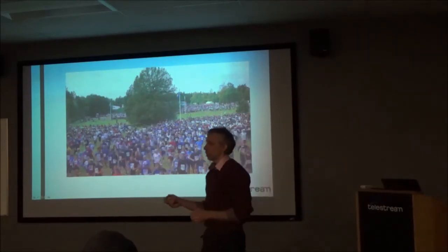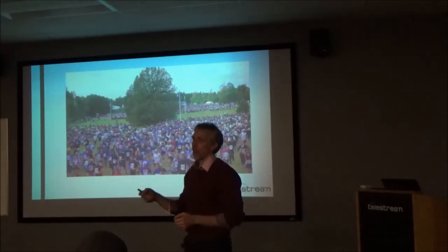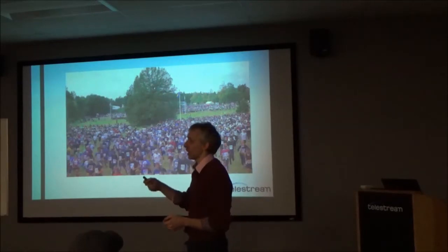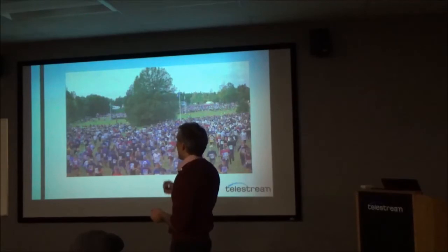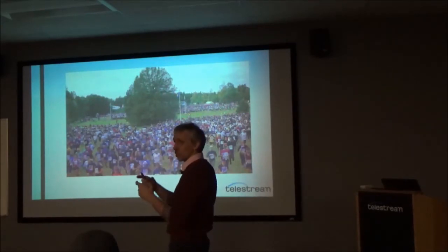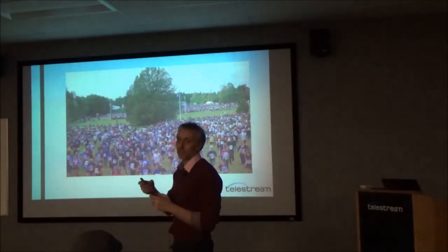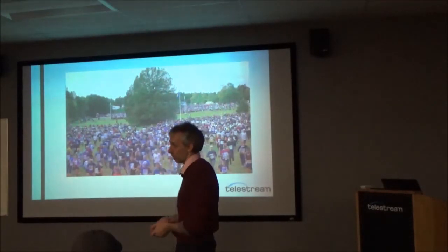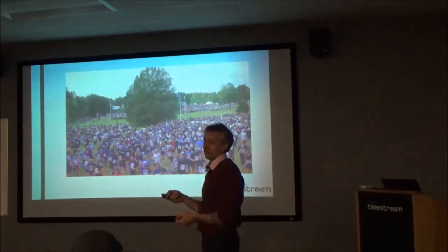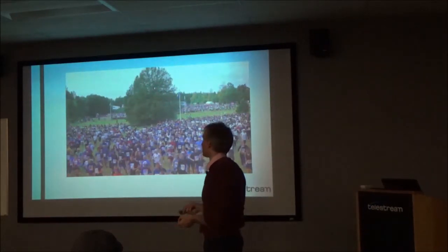So pointing to where in the previous picture I could pull that data from and not have to then send the same information again. Or maybe I use the previous picture to predict what that block's going to look like, and then I make some fine adjustments to it. But I don't have to send as many bits for those fine adjustments as I would if I sent the whole of the block. Everyone okay with motion vectors?